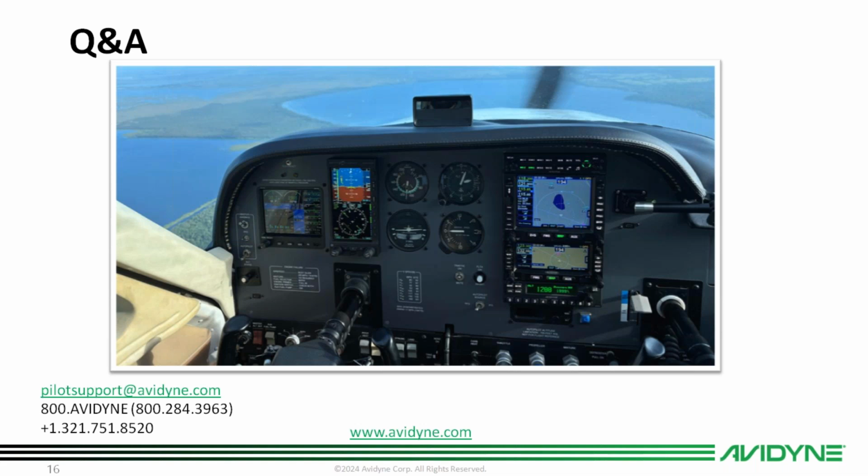I have a GDL82 and GTX 327. Do I need to upgrade to a different transponder? The 327 will be fine as far as transponder functions go, but for the GDL82, we don't have a protocol that'll work with that, unfortunately. Right, because the 327 is Mode C only. Yeah, you could put in a UAT and 978 in and out to be compliant, but the GDL88 won't talk to the Avidyne. It's on a proprietary protocol. GDL82, yeah, 82, sorry.